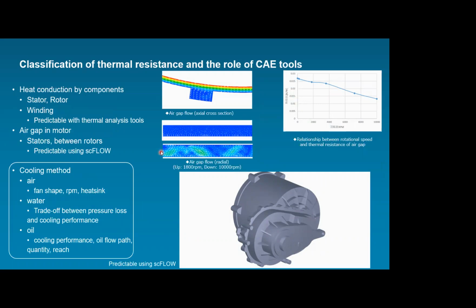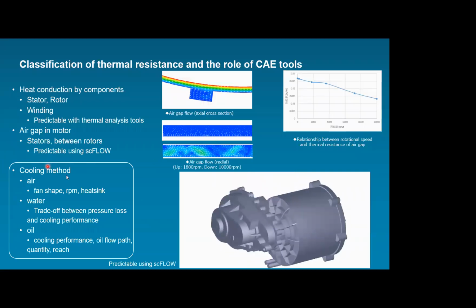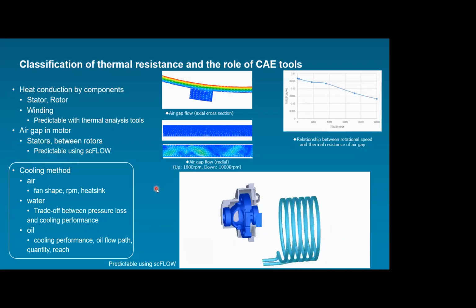So you can see that inside the CFD analysis, you can model very small and thin gaps. Actually, this is a zoom, but we are talking about millimeters or even less. And so we can accurately calculate all the distributions of the fluid flow inside these small cavities and evaluate in a very accurate way all the windage losses. And so we can also model the motor in a very accurate way, in a very efficient way most of all.